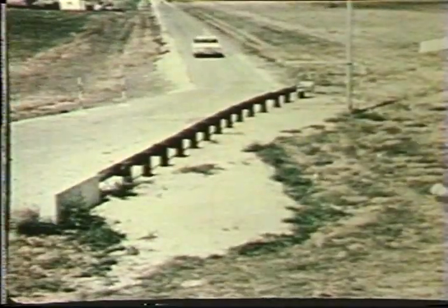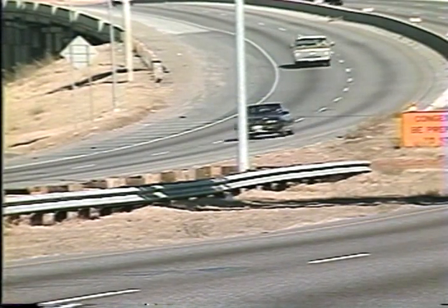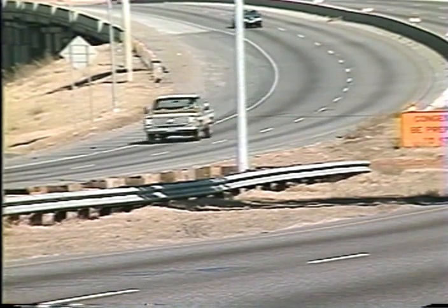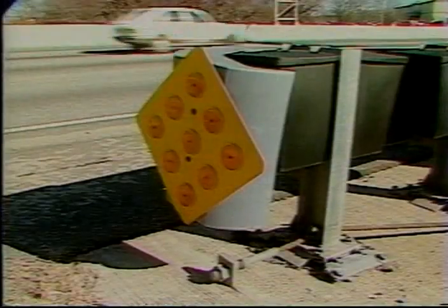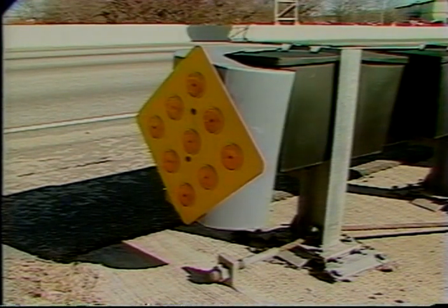Barrier systems are built to slow, stop, or redirect cars that hit them. This requires the design and construction of a barrier system that acts as a single unit when called on to do so. All parts of the system, the end treatment, standard section, and transition section, are important in supplying this required action. However, end treatments are probably more important than the other 2 parts.